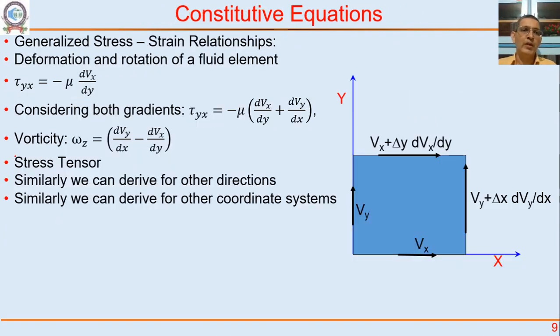Okay, let's go forward. So we are going to call these stress-strain relationships the constitutive equation, and this constitutive equation is linear right now. Stress-strain behavior is linear, and any such fluid that behaves like this is called a Newtonian fluid. Newtonian, it obeys Newton's law of viscosity. So most liquids that you will come across in everyday life are Newtonian.